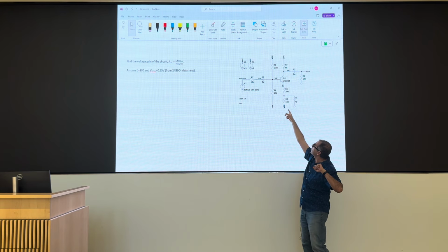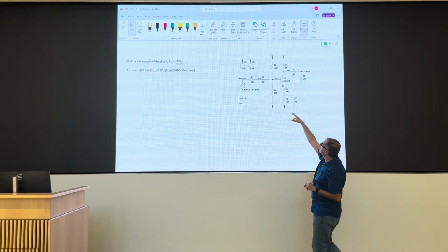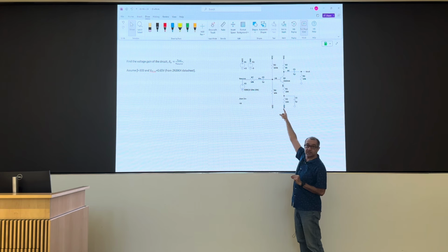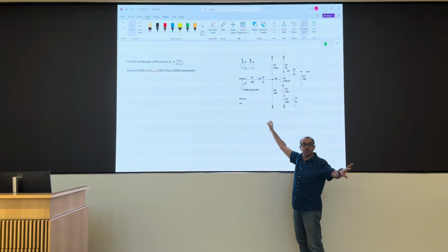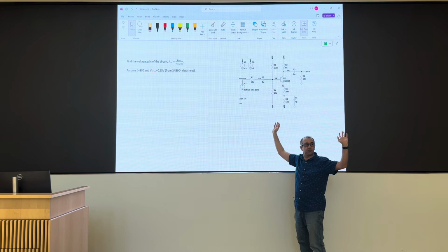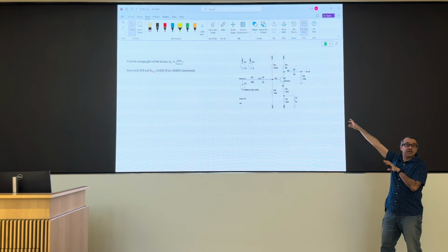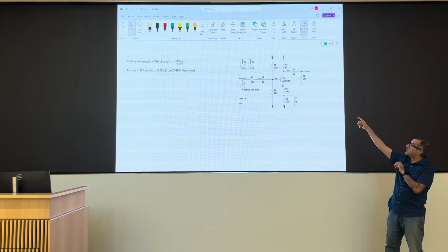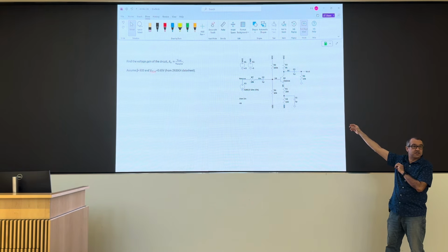If I don't use the capacitor at the input, for example, let's just see what happens. If I don't use C2, the DC voltage from my source is going to affect the DC bias point of my circuit. I don't like that because I do not control the source side. It may be some random DC voltage. At the output, if I don't put C3 there, if I change my load, it can affect the operating point of my transistor as well.